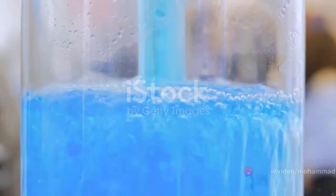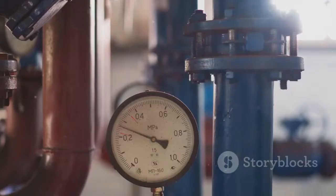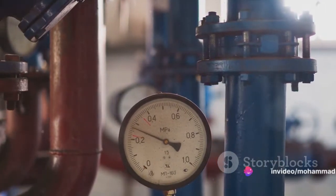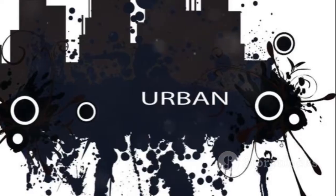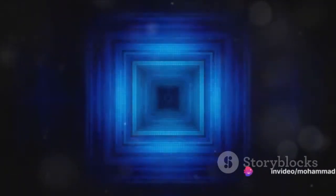As the fluid flow varies through the pipe, the orifice plate causes a differential pressure drop across itself. This pressure drop is not a random occurrence, but a calculated reaction to the changing flow within the pipe. It's a clever system, isn't it? However, it's not as straightforward as it seems. The differential pressure across the orifice isn't proportional to the flow rate. No, it's proportional to the square of the flow rate.